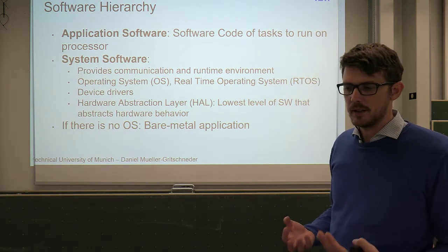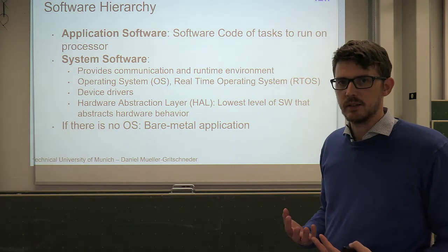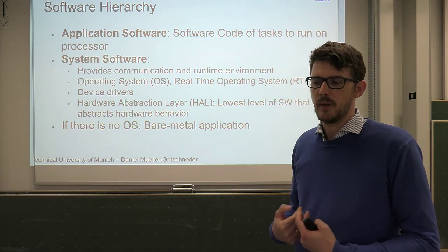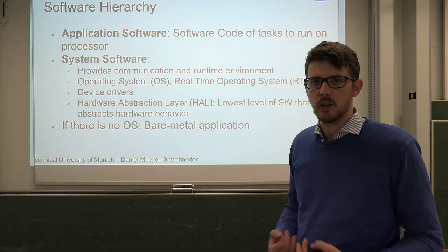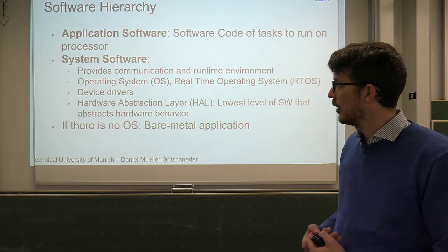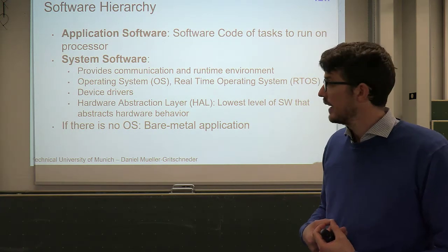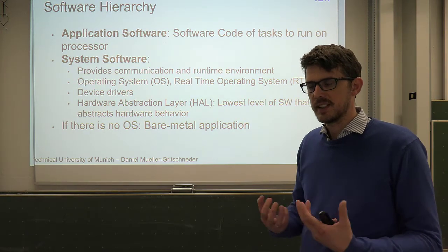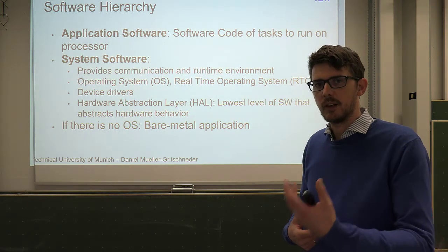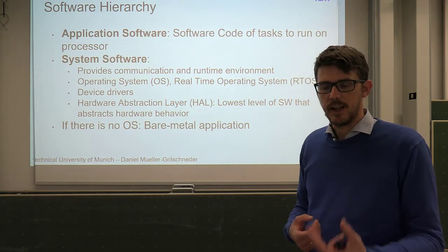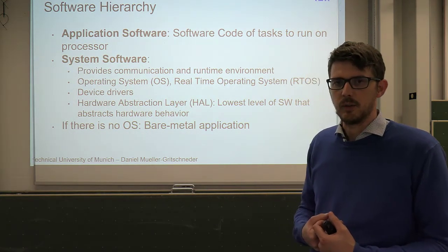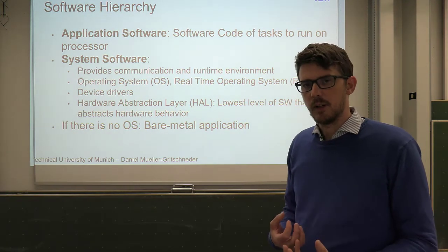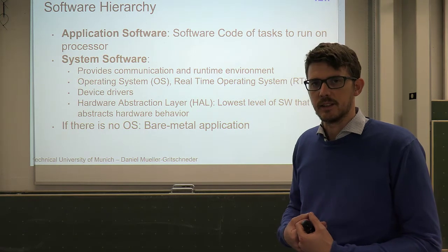The runtime environment is very often provided by an operating system or a real-time operating system in the embedded domain, where you can schedule tasks, react to interrupts, and so on. For communication with the different devices, each device has a software piece called a device driver, which is specifically designed to communicate with this hardware device. The device driver then runs on top of the so-called hardware abstraction layer, which is the lowest level of software that really does the accesses to the hardware.